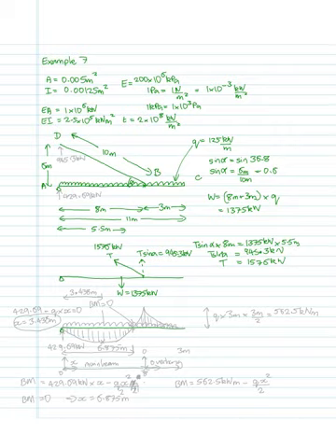So we would expect a parabolic bending moment from the end, going down like that. And then this bit here, we would expect that to come down like there and to go through here. Now, let's work out our reaction at D. So the vertical reaction at D is clearly the same force that we've applied in the tension.